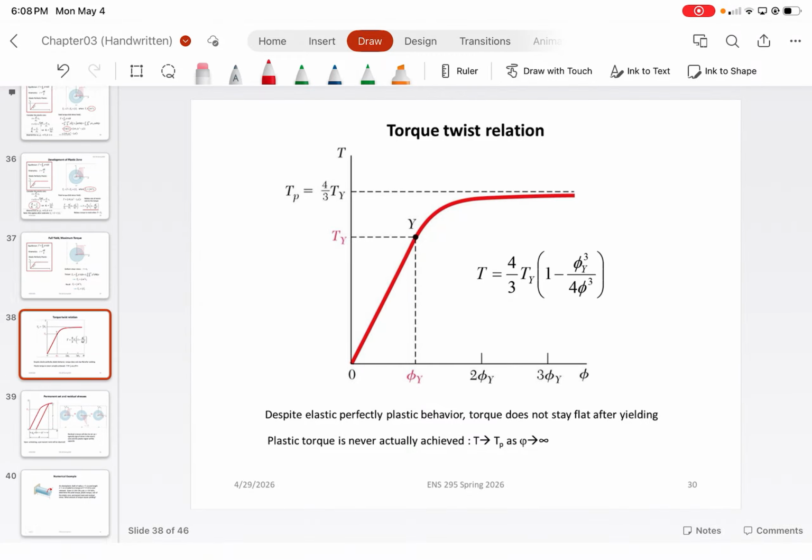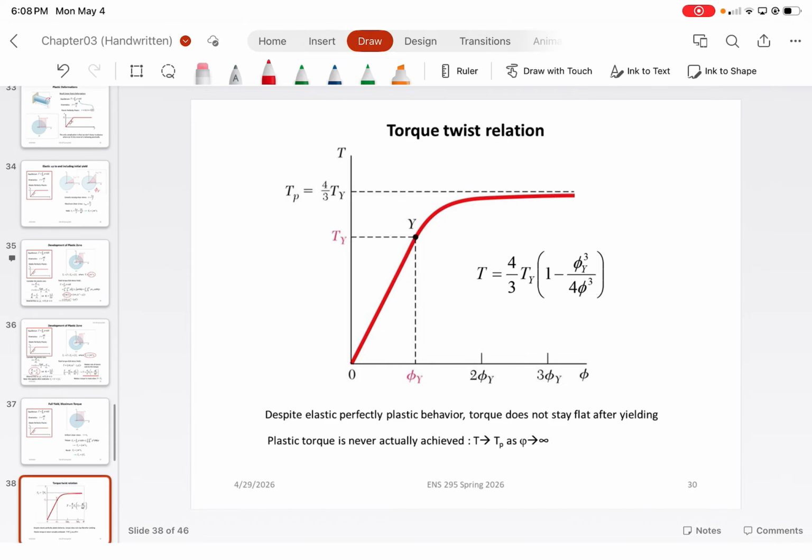All right. Anyone want to take a guess at what happens once the material yields and you unload it? Does anyone remember how it worked for axial loading? It would go back from wherever plastic strain point you went up to, and just go down at the same rate of change as it would in the elastic range.